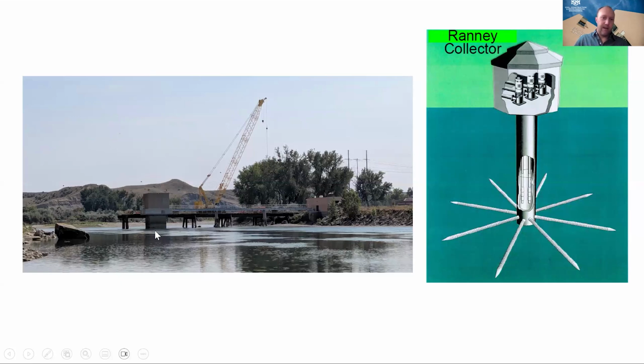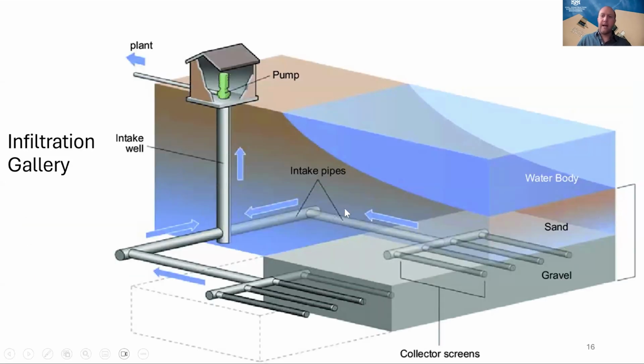Then down in the structure is a pipe that has a bunch of perforated pipe that goes underneath the sediment. And you can see the schematic over on this side. So the pipes go down into the river, and then all these perforated pipes radiate out, and the water flows into these perforated pipes. And these perforated pipes are underneath the sediment, and so that sediment acts as a first layer of filtration, actually. So the water that's being taken up, flowing into these perforated pipes, is generally higher quality, a little more filtered than the water in the river, for example.